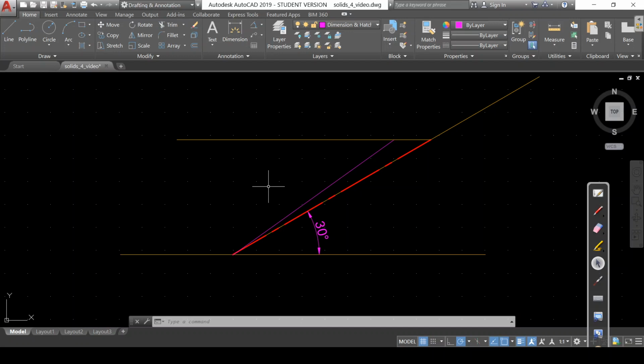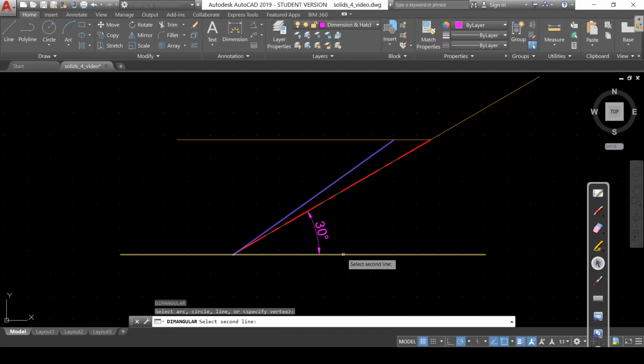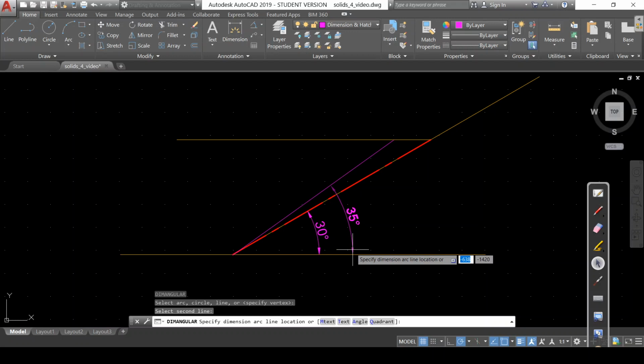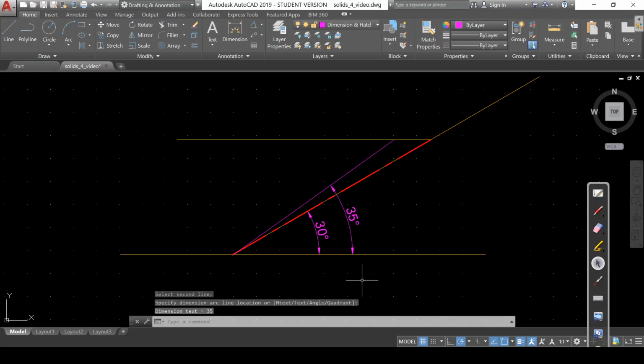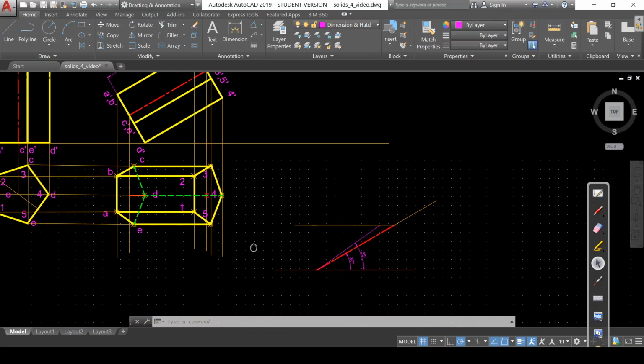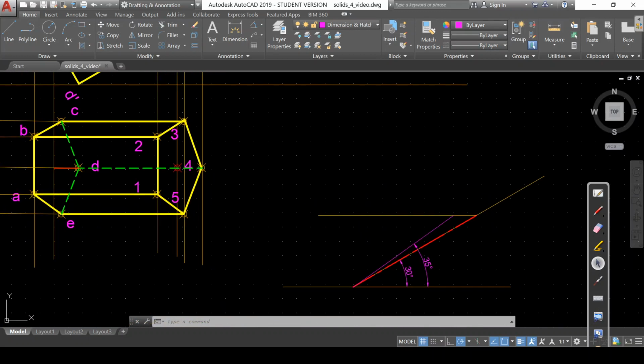You can recall that. Now same angular dimensions between this apparent length of the axis or elevation length and the XY line. So approximately it is more. Always apparent angle is more than the true angle. So we have got the apparent angle. If they ask the question, you can measure this and give the answer that this is the apparent angle. But now they have not asked the angle. Instead, we have to reorient the top view at this apparent angle and then take the projections for the front view and complete the front view.